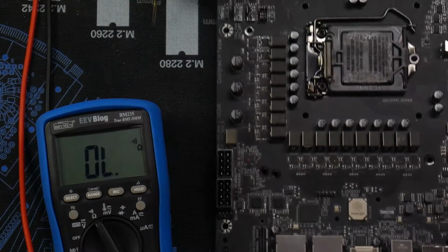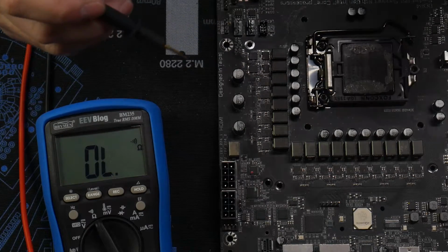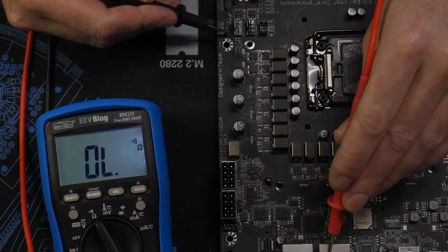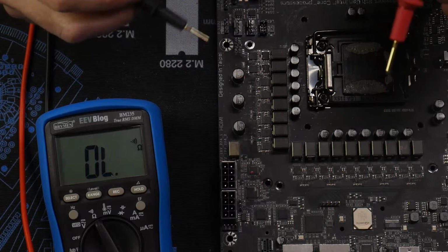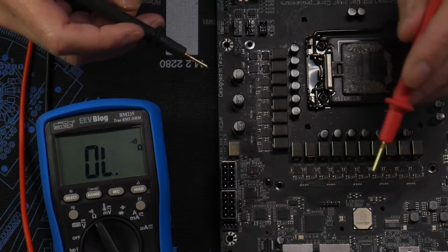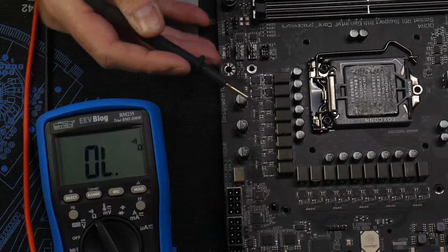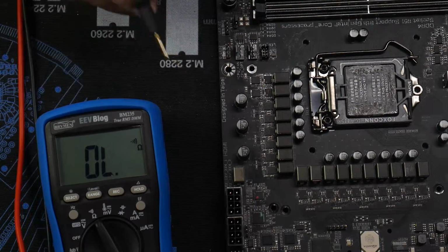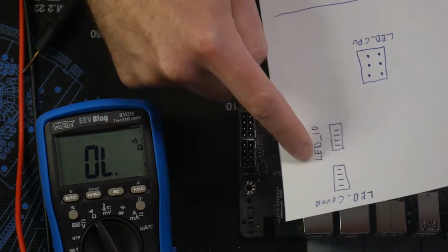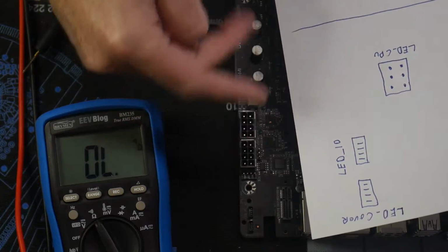That's one thing to keep in mind. Addressable LEDs will always have a ground point, and that will always be connected to every other ground point. And analog won't. So that's one way we can figure out whether it is digital or analog. And we're going to use the digital LED header right here to figure out what is what. So what I'm doing is I'm writing the silk screen where it matches the header. A lot of these have the silk screen, which will be white usually if your board's black.